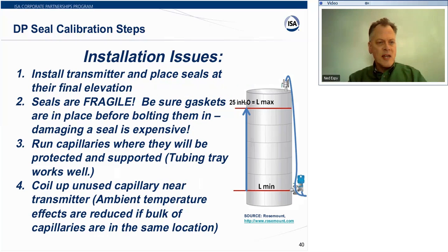Focusing a little bit more on installation, you want to make sure that everything's placed properly and matches up to your calculations. Let me emphasize, those seals are fragile. You should always be using gaskets and make sure they're in place before you start bolting down and damaging an expensive seal. It's a big headache to have to send these things back, or you just end up throwing the old one away.